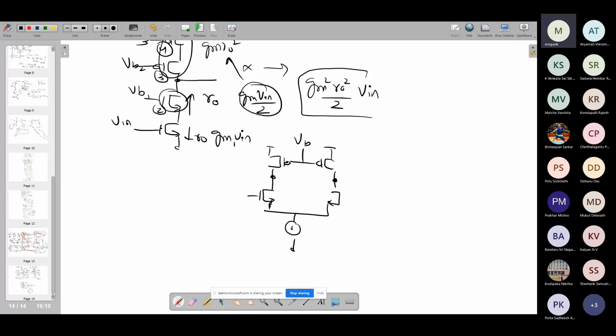So here, in this particular amplifier, suppose the output DC point is taken care of, you have biased it somehow using common mode feedback. In this case, whatever small signal current is produced, suppose VD minus VD, differential signal, this is AC ground. So GM VD by 2 minus GM VD by 2. The same small signal current goes into the PMOS, and then we get an output over here. However, when we connect the current mirror load, what we are doing, that also we have discussed.